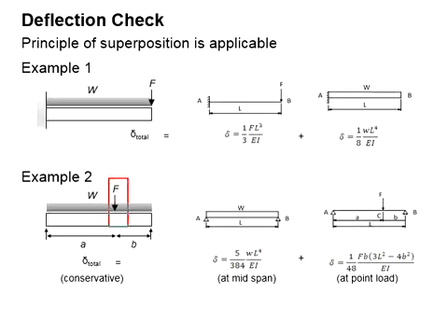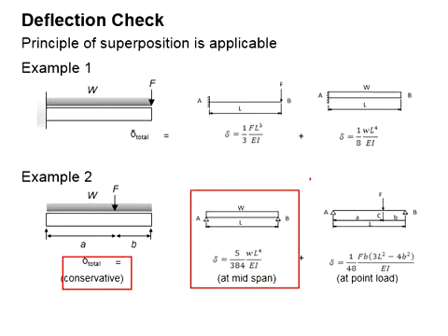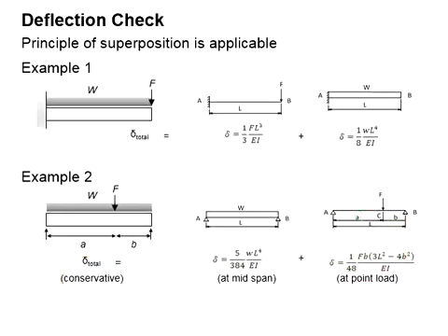This point load is not acting at the center of the beam. The maximum displacement for the UDL will be at the midspan, while the maximum deflection for the point load is actually below the point load. They are not happening in the same place. You may conservatively assume that the total displacement is determined by the summation of these two equations.